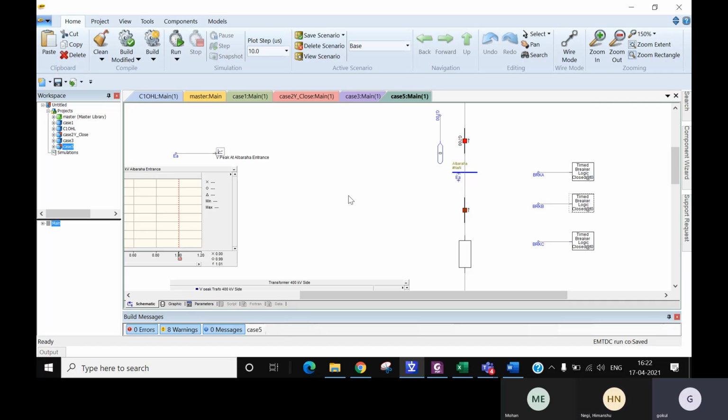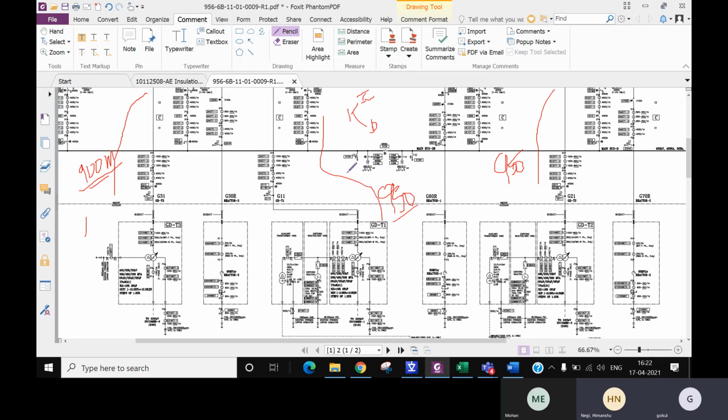But the issue is you have to frame your cases based on the shortest path and longest path. So this is important. And the other thing is, from this generator circuit breaker, you have to know what all components are there, and you have to model those components as a nominal pi method with the measured length of it. That is again an important thing in ferroresonance.